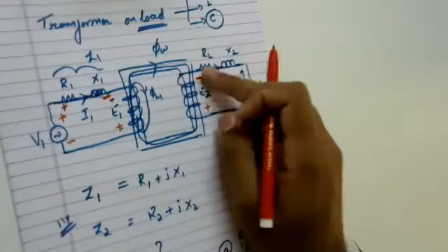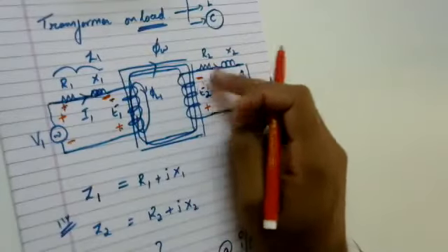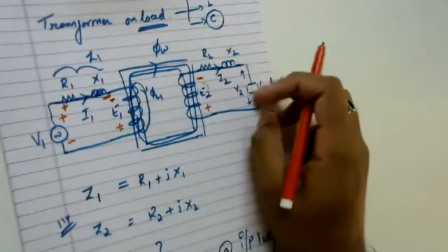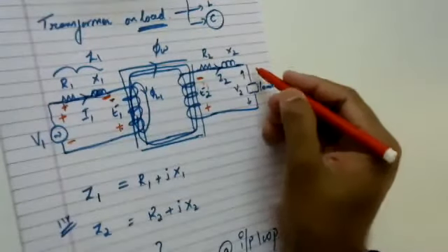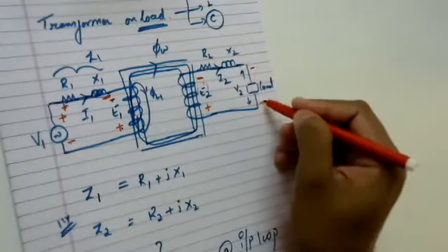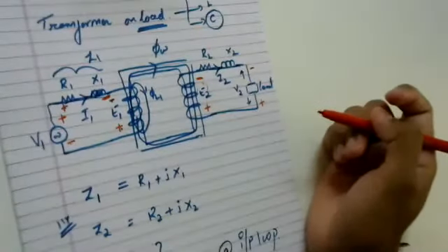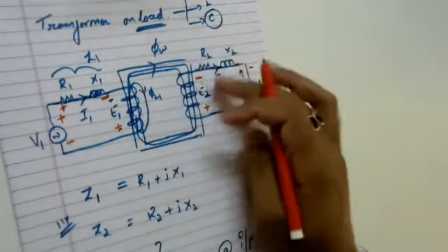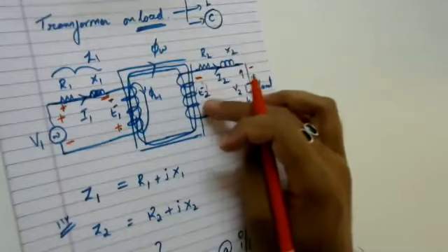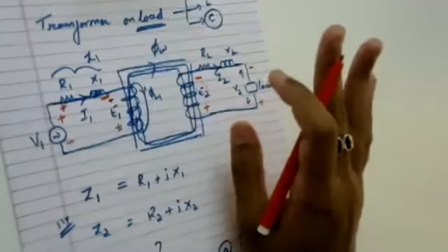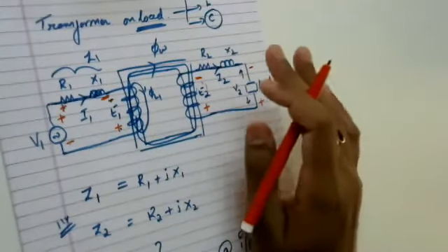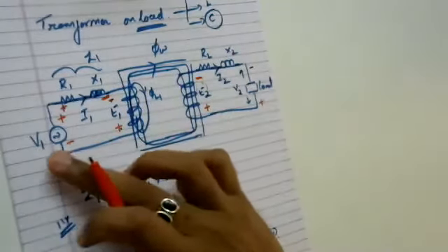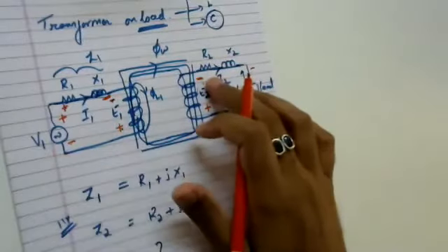Whatever is the polarity on your induced EMF, the same polarity exists onto your load, so your load will also have negative, positive. One thing you need to understand is that onto your secondary loop, E2 is acting as a source. This is a very important point, because there is no physical interaction between your actual source and the secondary circuit.